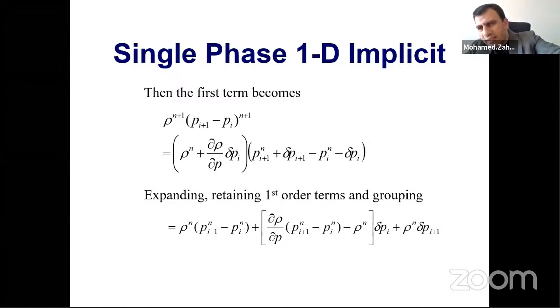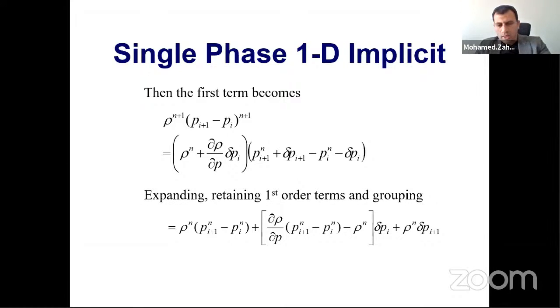But the volume itself, from the static point of view, is the pore volume, which is the porosity multiplied by the area multiplied by the thickness. Usually, when you are calculating this, you need to use the Bo to convert from reservoir to surface, and this Bo is changing with pressure.